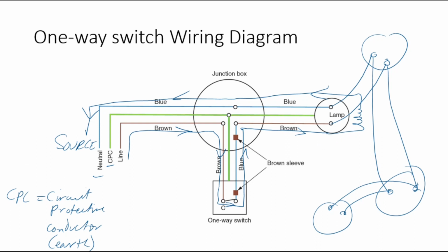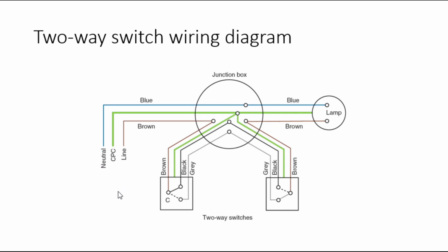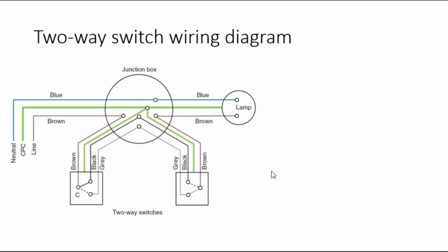But in some cases, you would want to have more than one switch. So here we have a two-way switching diagram. So your circuit looks like this. So let's redraw it a bit. If this is a live wire, it would first encounter a switch, one switch like this, right? Notice that it has two connection points. We call it two throws, okay? It can either be connected to here or it can connect to here, which is what we've indicated on this point. And the connection around this junction box can be simplified to look like that, right?